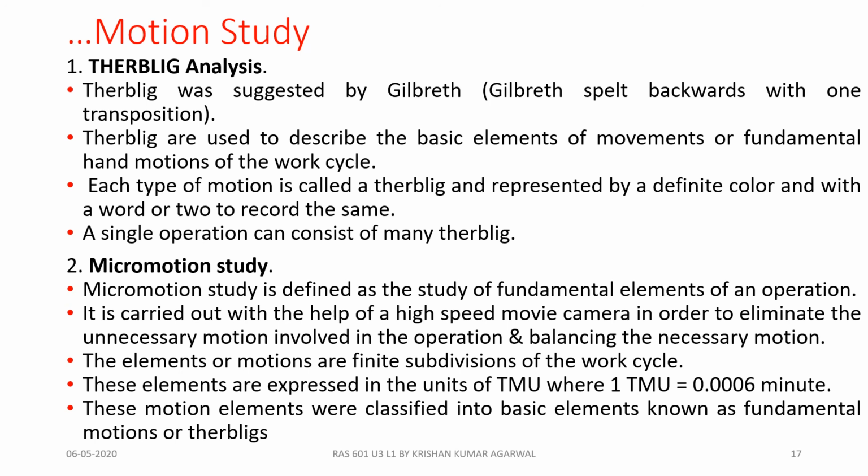These elements are expressed in units of TMU, where 1 TMU is equivalent to 0.0006 minute. See, students, how a high quality movie camera is used to study the micro motion of the worker.